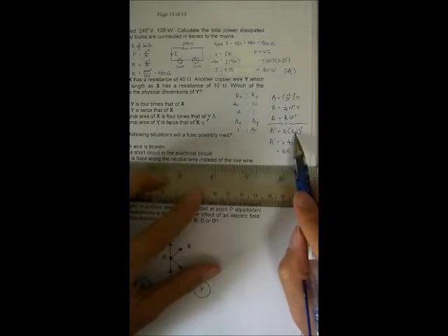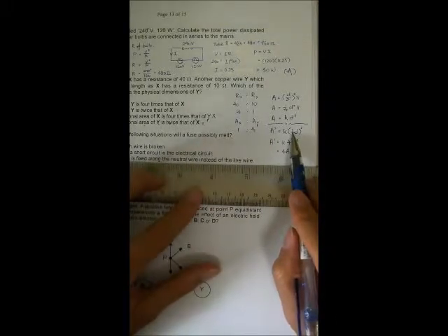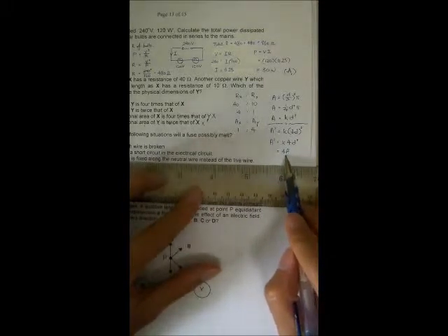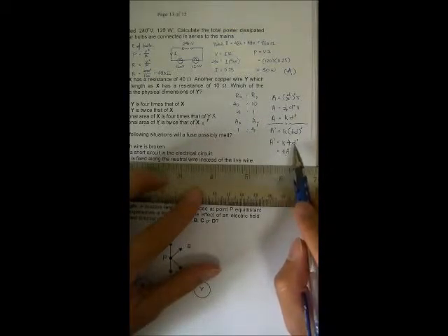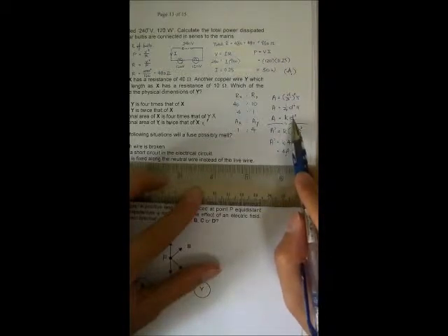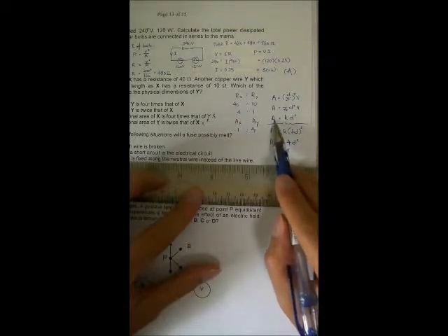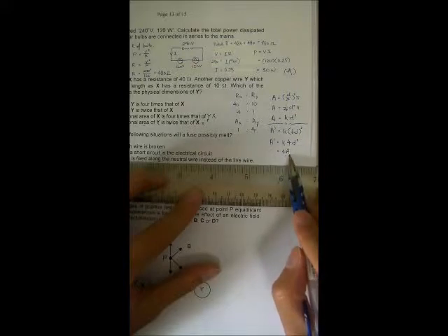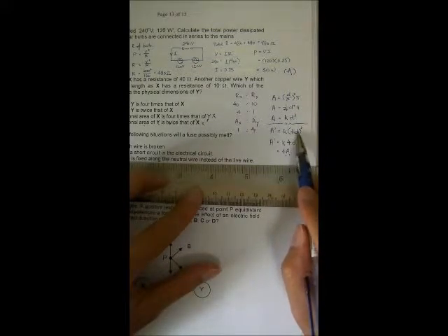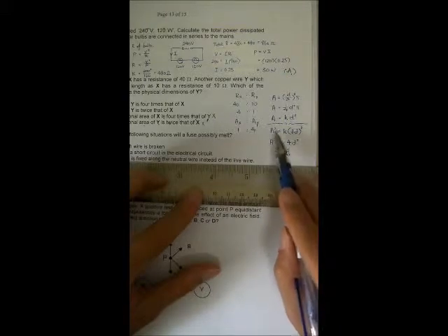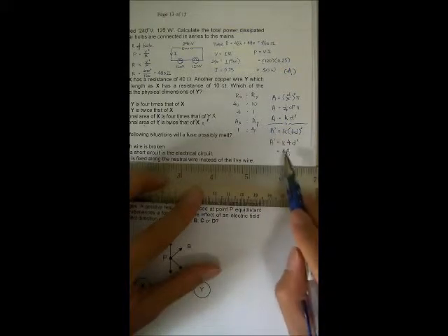So when you increase the diameter by 2 times, you are actually increasing the cross-sectional area by 4 times. What I'm doing here is that this is kd², this is also kd², and kd² equals A, so I can put this as A. So by increasing the diameter by 2 times, the new area equals 4